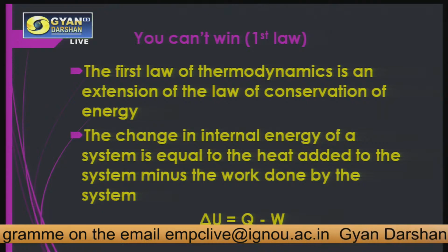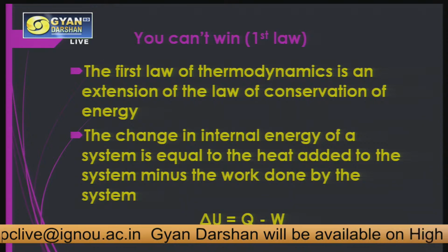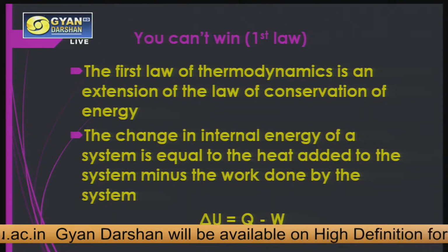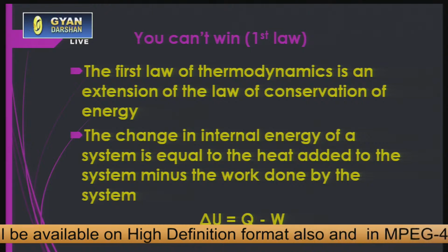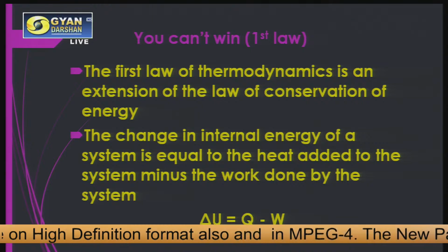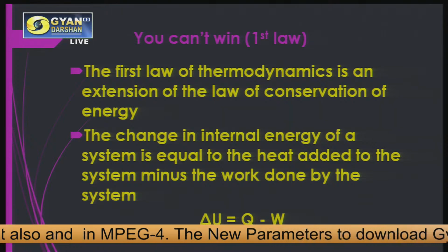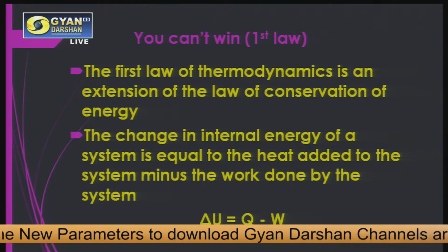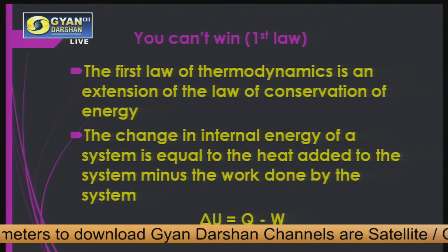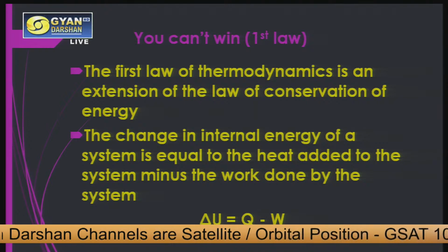In the mathematical form, generally we say that whatever heat is transferred is equal to the work done by the system. So if we talk about the change in internal energy of any system, it is equal to the heat that is added to the system minus the work done by the system. Here, sign convention is very, very important. If heat is added to the system, it will be positive, and if heat is extracted from the system, it will be negative.